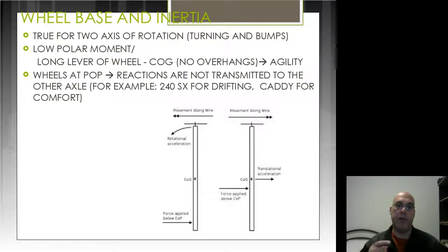Imagine the rod is hanged at one wheelbase and we hit it at the other wheelbase, and you don't want the rod to move at the other wheelbase. So any reaction at one wheelbase is not transferred to the other one if you are at a point of percussion.